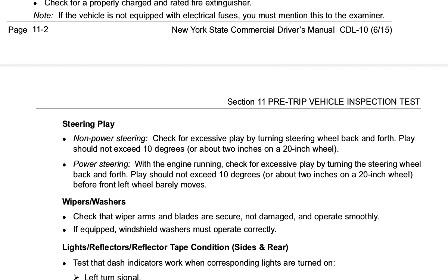Power steering. With the engine running, check for excessive play by turning the steering wheel back and forth. Play should not exceed 10 degrees, or about 2 inches on a 20-inch wheel, before the front left wheel barely moves.